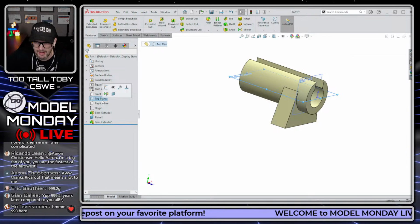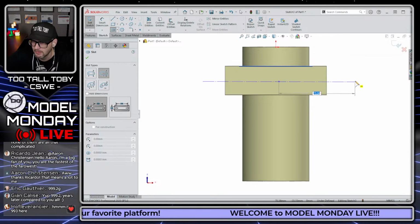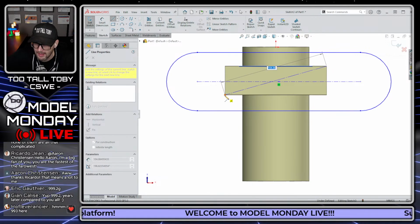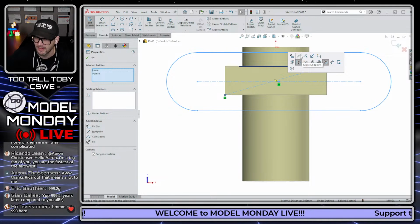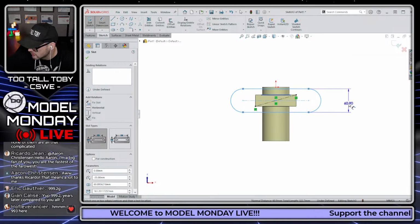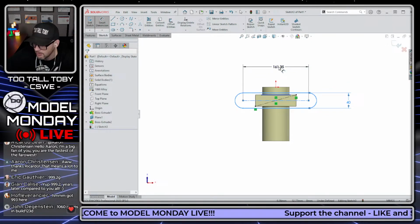And now from that leg one, we can select that face, begin a sketch, orient our view, and create our slot. I'll just do this with a center point slot to create this geometry, and then I could draw a line corner to corner here so that I can pick that line, hold control, pick that center point slot center point, and then choose make midpoint, and that way that slot is centered on that foot. And then I can give this a width of 40, and then the center to center distance for that first one is going to be 135.